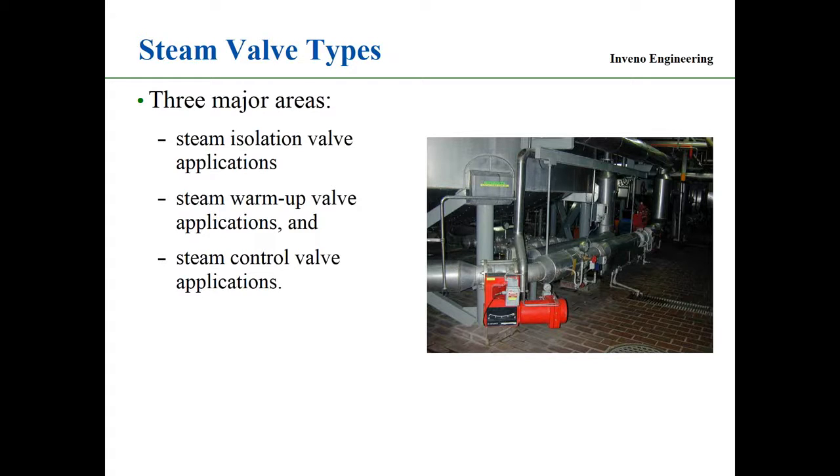The next one is the steam control valve application, supplying steam to the plate and frame heat exchanger, the shell and tube, the steam coil. We want to make sure that it's not leaking through. And the other thing is when we set up the control loop, I'll be talking about this, where's the breakaway point of the valve? The breakaway point is when the valve will start to pass steam through it.